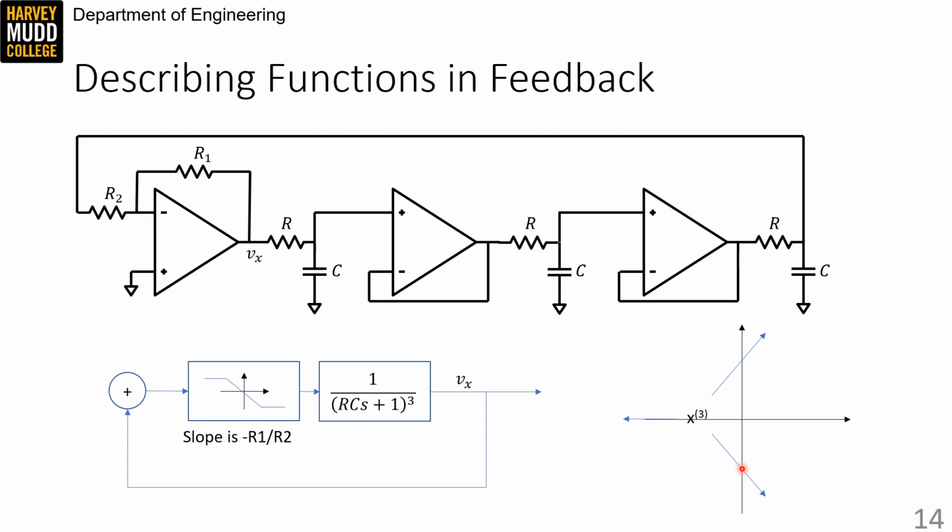This analysis also tells us we're probably safe using a gain larger than 8 in our value of R1 and R2, which means that our poles would start in the right half plane rather than strictly on the j omega axis. However, as the amplitude of our oscillation gets larger, those poles will get forced back onto the j omega axis as the describing function saturates the gain.